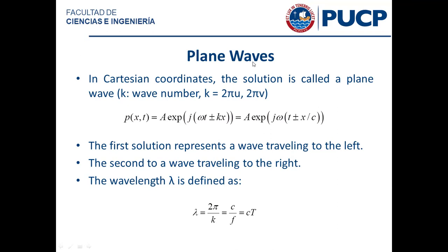And as I said, that's what Emilio was saying. Maybe because when we have ultrasonic waves, they look like sinusoidal oscillations? Yes, and my answer was yes and no, because regardless of that, they have a duration. Because they have a duration, it simply cannot be that they correspond one-to-one to a purely harmonic oscillation. They would have a bandwidth.